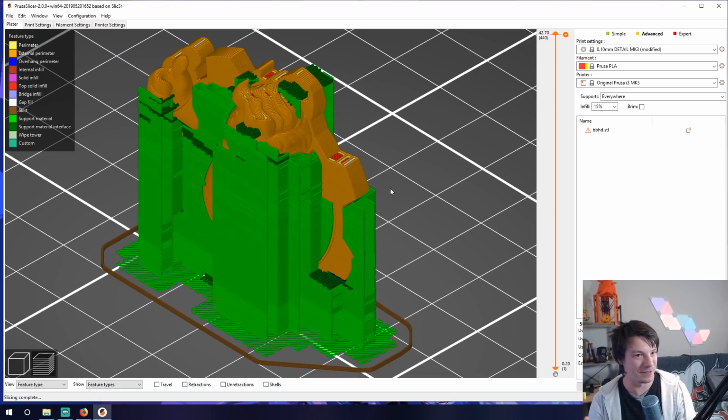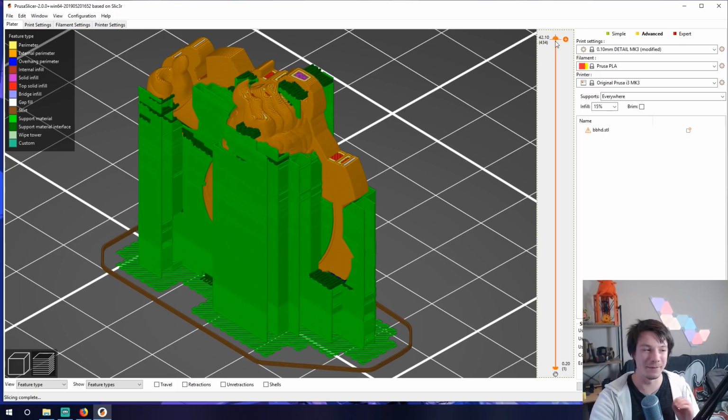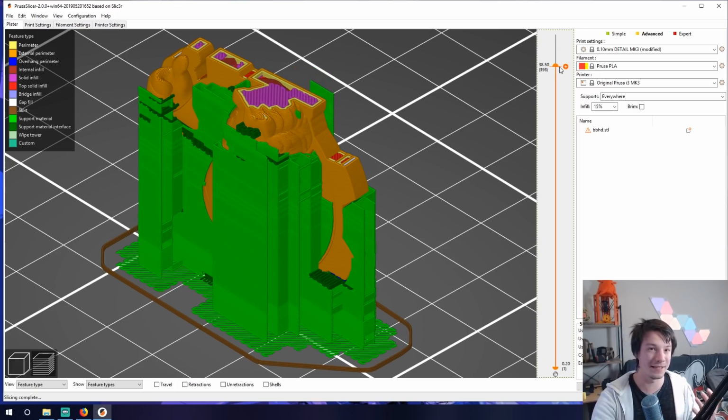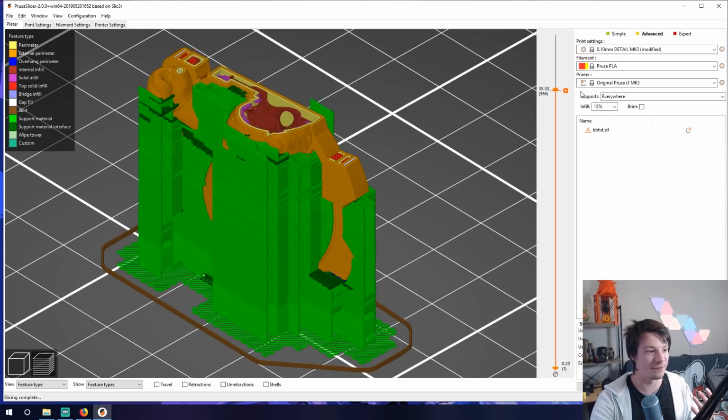Okay, it looks like a lot of support material because it's vertical. If you put it this flat, there would be a lot less support material, but the detail won't be there. You get much higher detail with FDM in the vertical versus the horizontal. Because remember, it's still a 0.4mm nozzle, but we're printing now at 0.1mm layer height. So that's a 4 times detail increase that we're able to achieve.